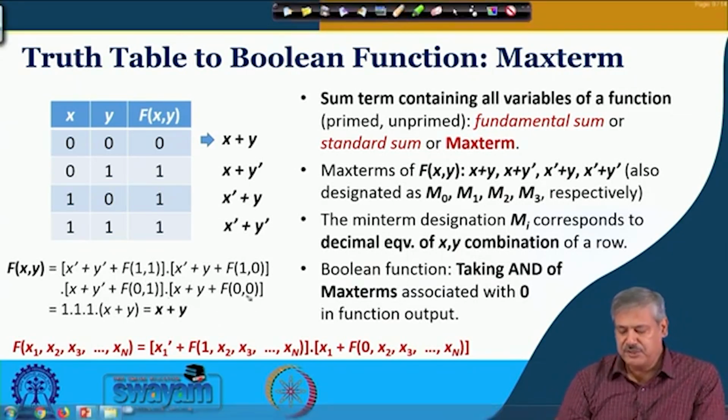Only we know that f 0 0 was 0 and the rest of the terms were 1 by calculation, and then when you do it all individual terms will generate 1 and only the last term will generate 0. So, 0 plus x plus y and the rest of the terms are all 1. Okay. So, that gives you x plus y. So, this is what you are getting from the nested version of Shannon's expansion theorem, this dual version.